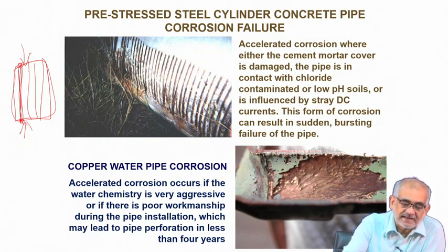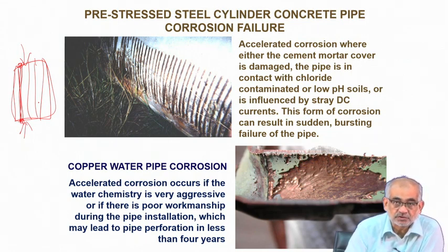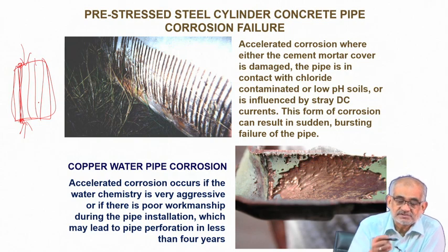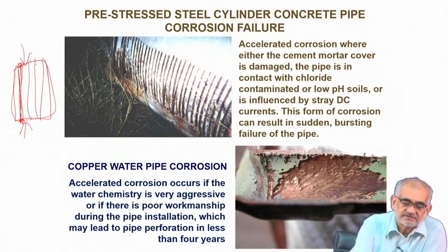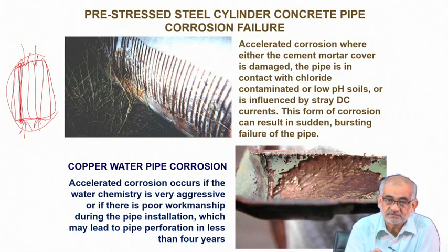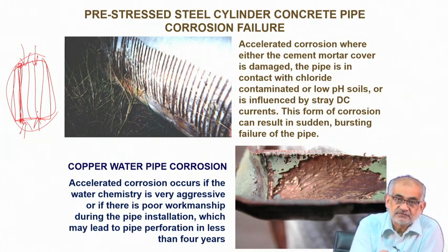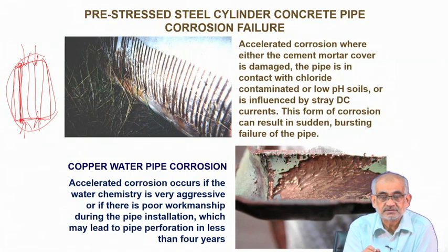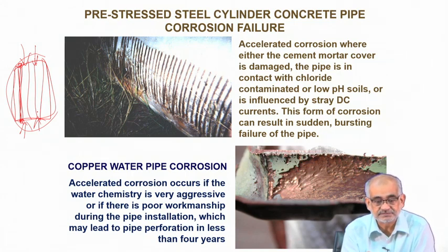So when they try to relax, they try to stretch along with the concrete, but by then the concrete is all cast and frozen, so it cannot allow the rods to stretch anymore. So in the process it develops a residual stress on the surface, which acts in the opposite direction, or compressive in nature. Now, even in order to get this effect of residual compressive stress, use of such reinforcements which produce residual compressive stress is very important.